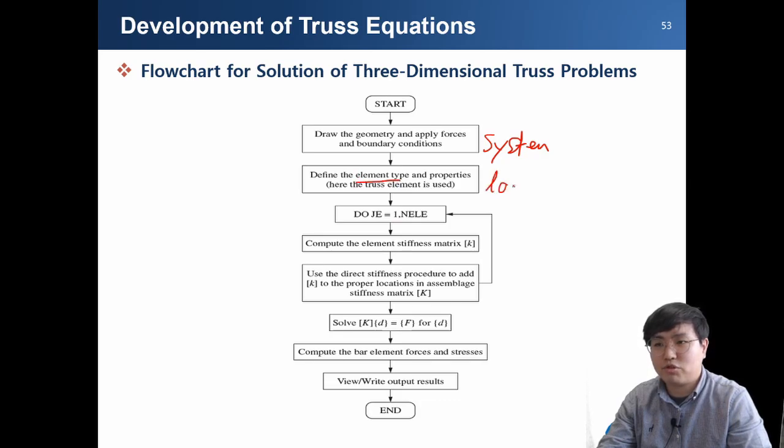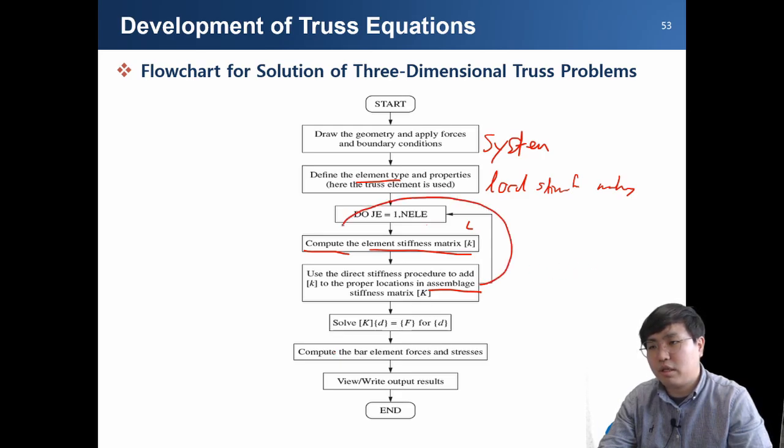First we should know what kind of local stiffness matrix or equation to use, and then discretize our system very finely, compute the local stiffness matrices, and then assemble these local stiffness matrices into the global stiffness matrix. This takes some time depending on your number of elements.